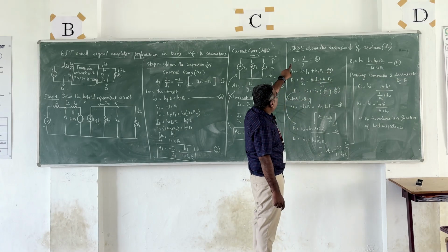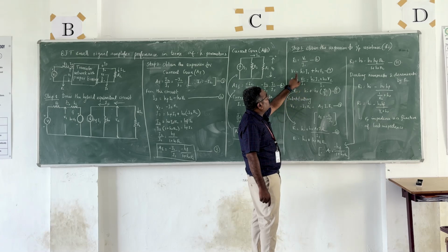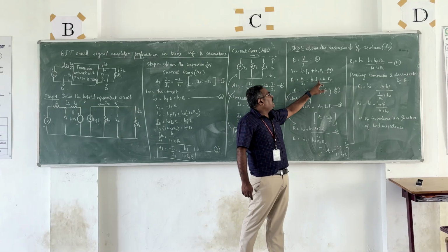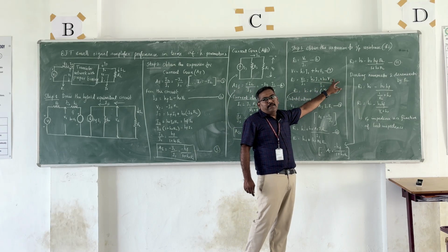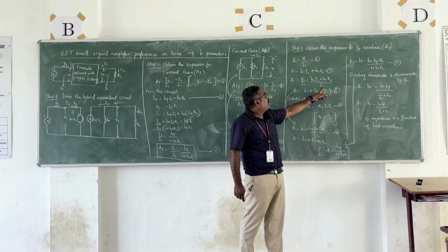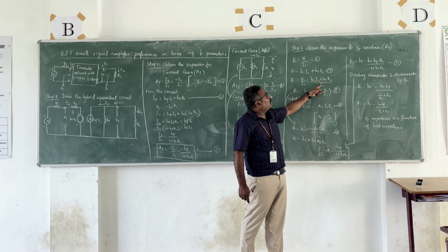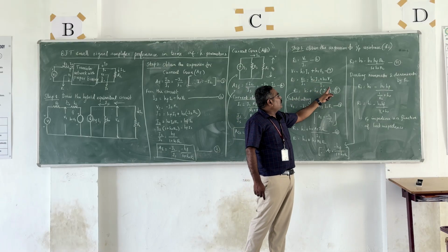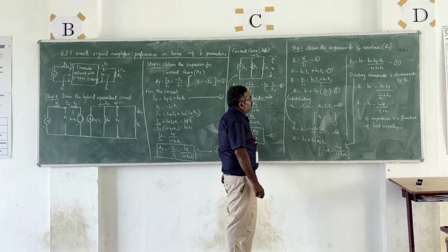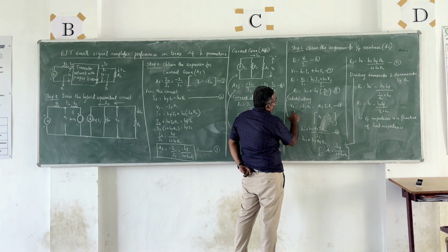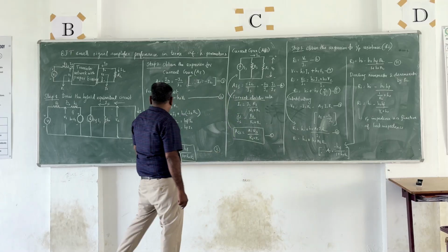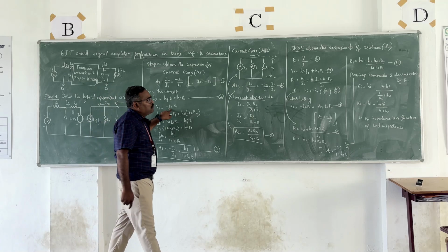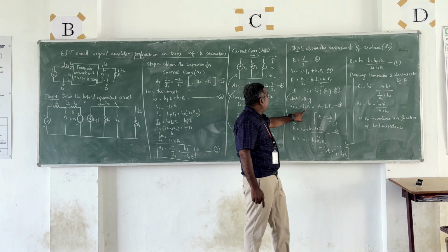Okay. So we know RI is equal to V1 divided by I1. Already we calculated V1 using that equivalent circuit, HI into I1 plus HR into V2, divided by the actual I1. Your RI is equal to, so these two I1s cancel each other: HI plus HR into V2 divided by I1. Substituting, we already know the V2 value. Your V2 is minus I2 into RL. So we are going to substitute.